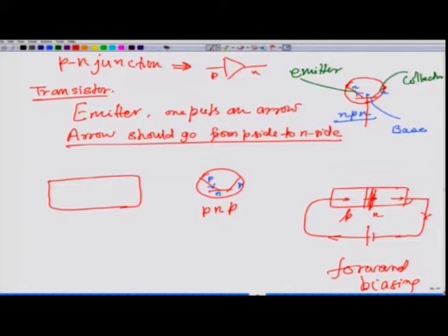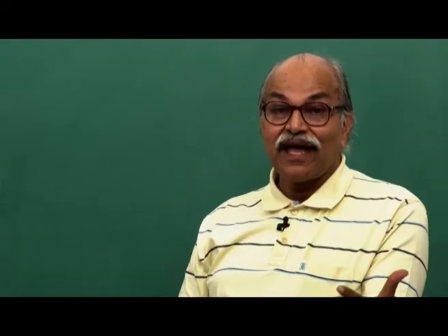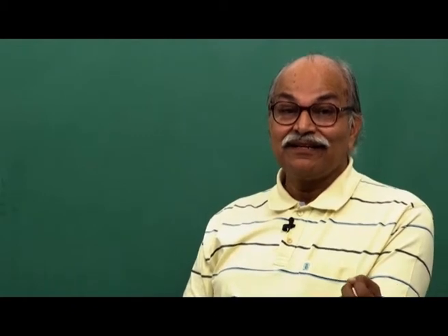If you think of that silicon base where you have these two junctions and then the depletion layers and all those things, and if this is your NPN or PNP transistor, you must have some metallic contacts. So, you should show the contact somewhere at this end, somewhere at this end and somewhere on the base. So, you have 3 metal contacts to connect to the outer circuits: base, emitter and collector, all 3 need metallic contacts.